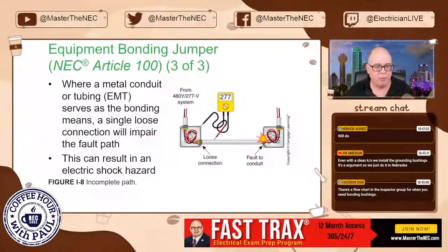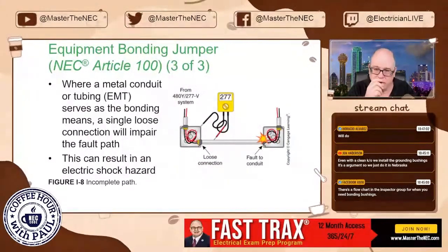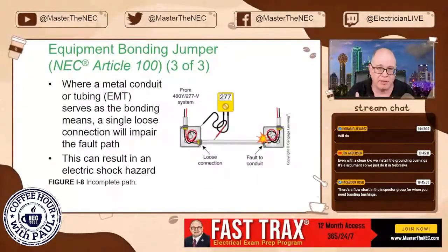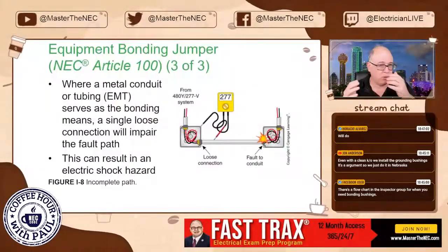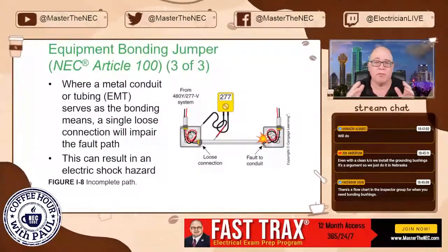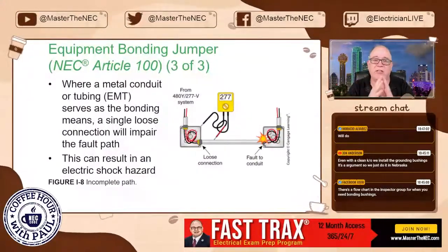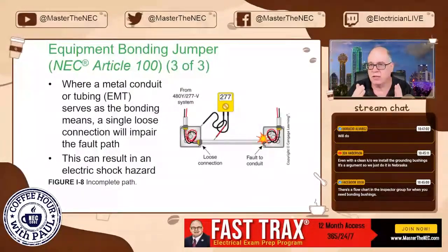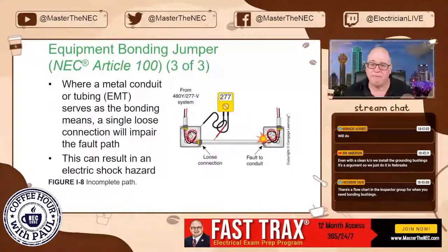And you do have people that might get a little lax on making those lock nuts tight, or putting on a coupling properly, or the coupling could move if you don't think about expansion and contraction depending on where you install it. Maybe you're on a bridge or something and you don't follow the rules for expansion and contraction and it moves, and you could have a coupling pull loose. So at the end of the day, a lot of engineers just want the wire because they feel better about it.